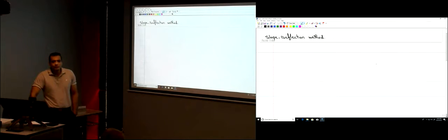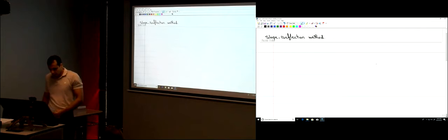For a determinate beam, it's easier to use the methods that you used in structural analysis 1. Just use the equations of equilibrium. You don't need to use the slope deflection method to find the internal forces in a determinate beam. You can use it, but it's going to be just more work that is not going to give you any extra thing, okay?